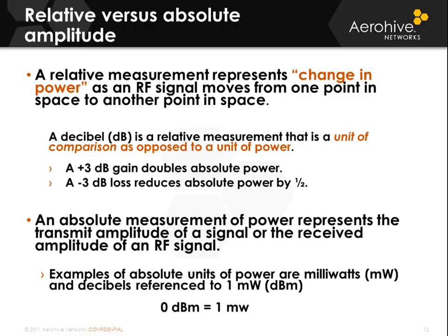There are pieces of equipment that you can spin onto a radio or a cable that will measure the amount of power that is actually being intentionally pushed into the antenna. That's your intentionally radiated power, and that can be an absolute measurement. When you add the antenna into the mix and it is propagating into the air, then it's going to be a relative measurement as it propagates out to the client.